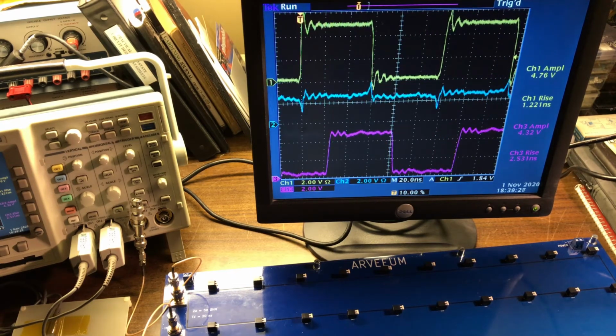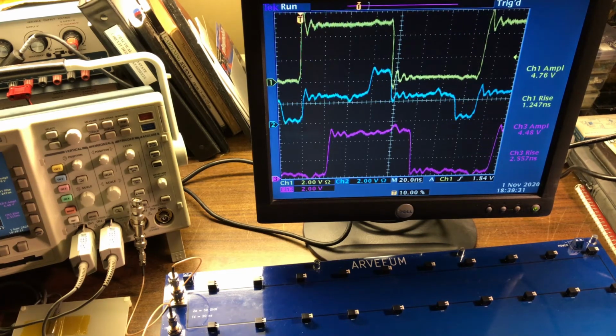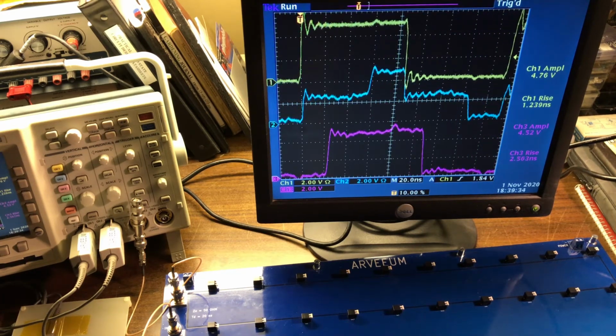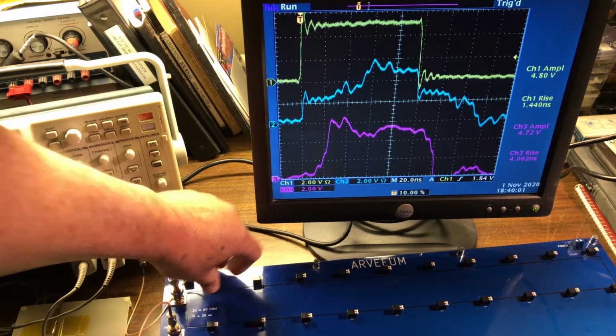and they're usable. So I just want to point out, because I've seen cases where clocks in boards are horrendous because people have not taken care of the return path of the current in the boards for high-speed signals inside the boards, or in this case, a microstrip. But I've seen it done in strip lines inside the boards, and the signal looks horrendous, just like this.